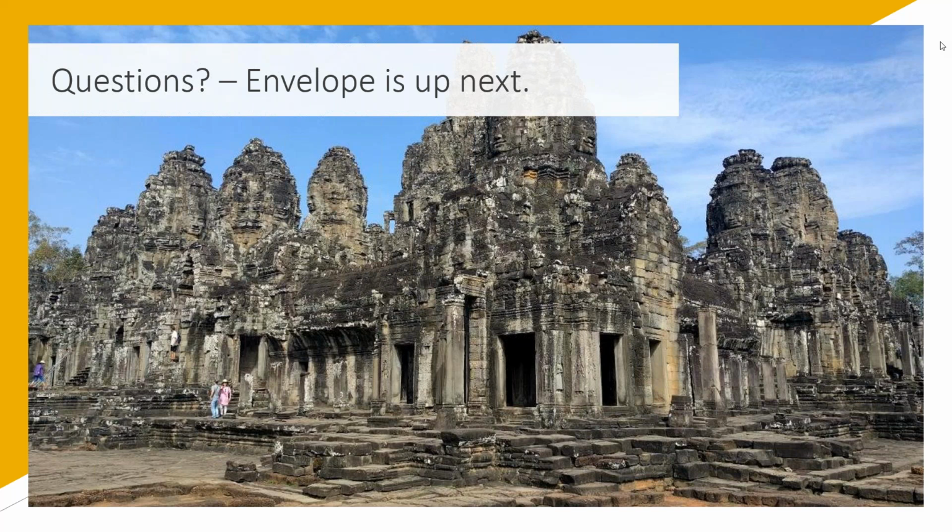I think it's a give and take in that sense, depending on the type of software you're using. For example, in New York City, if you're doing prescriptive, you can use what's called ComCheck, which is a commercially available software where you pick your baseline and fill out all of your details, and it'll kick out a compliance sheet at the end. If you're using IES, for example, it has compliance paths built in as well, both for 90.1 and for other standards. So it depends on the software you're using.